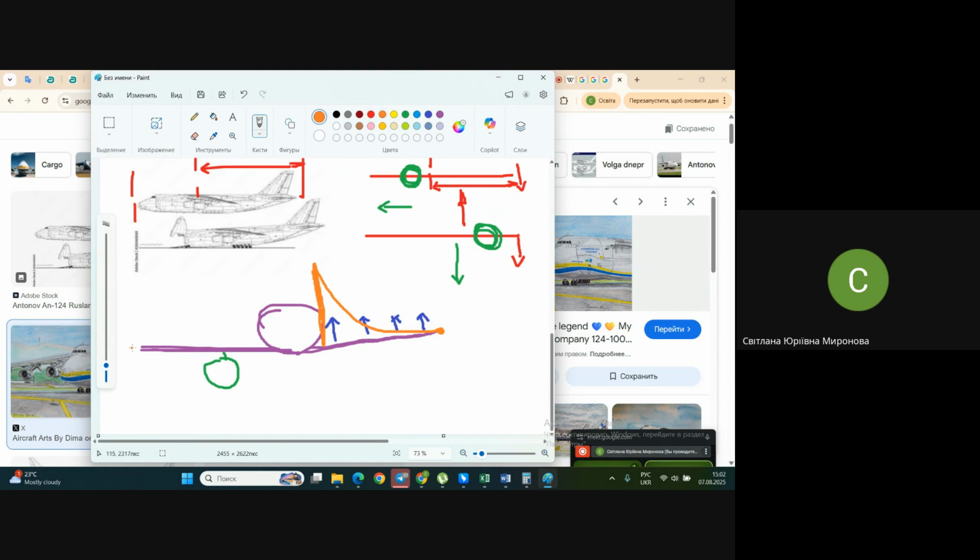In this case, the bending moment up to the engine grows like this, yes, as it was, but where the engine creates a counter moment, like an additional force has appeared, it's like a counter moment is created. And it means that the general distribution of inner forces will be like this. Maybe not as significant as I draw it. But at the place where you have the engine, it changes this gradient. It grows already not so significantly.